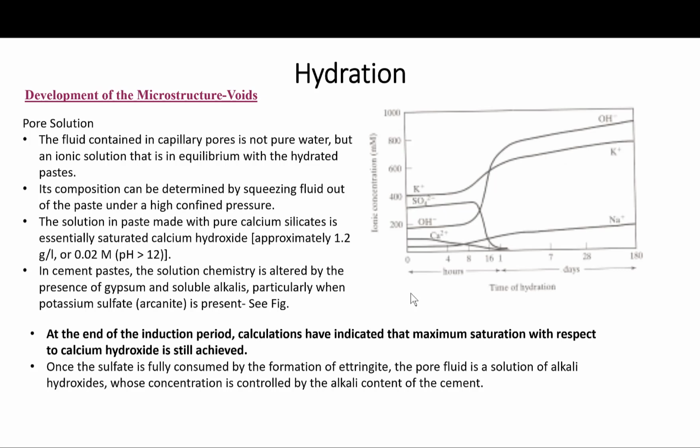Its composition can be determined by squeezing fluid out of the paste under high confined pressure. I have done that, and it's a very interesting process, and it gives a wealth of information about the ions and ion concentrations.